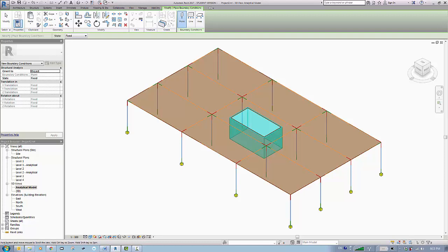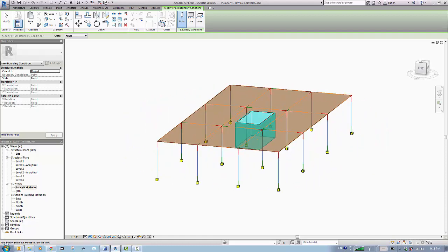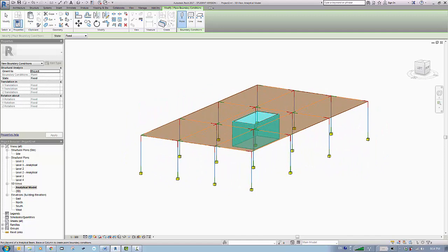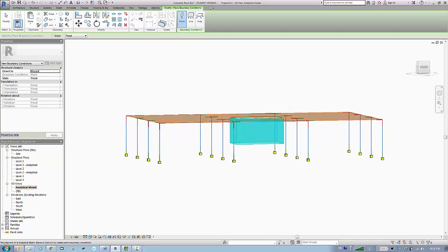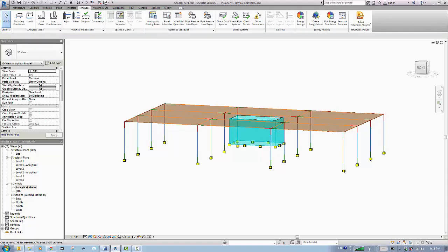The only thing you will make changes to is the column sizes, because the beams, main and secondary beams, are typical if your floors are same. If you have typical floors, then they'll be the same, so you don't need to repeat them all over again, especially if you have a complex project. So just copy. And for the shaft, we'll use line boundary fix again. Now this side and this side, this side and this side. So good with the supports.